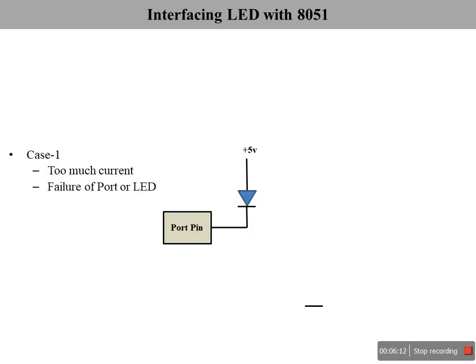Coming to the first case, here is the LED. It has a cathode which is connected to the port pin, and the anode can directly be connected to the power supply.